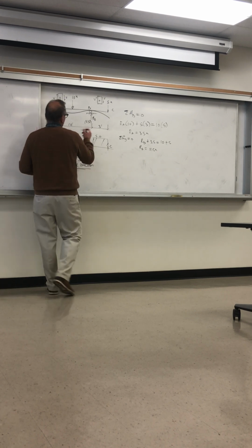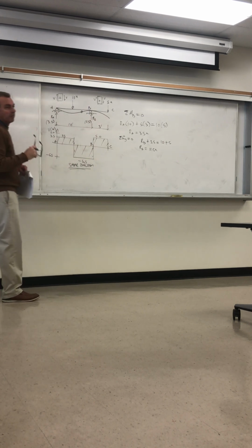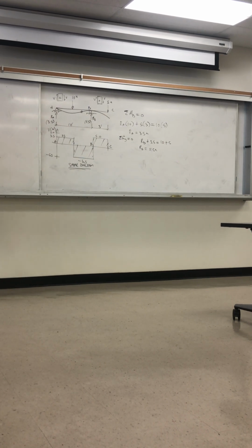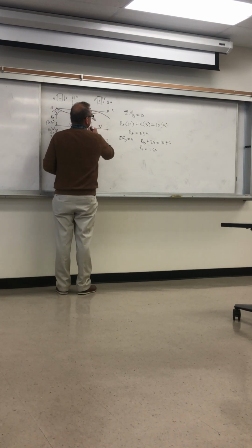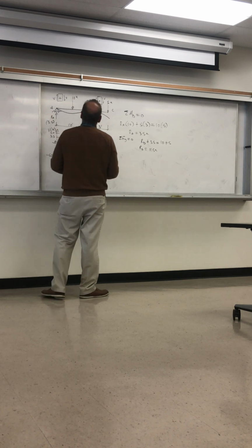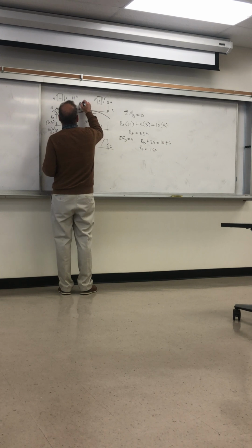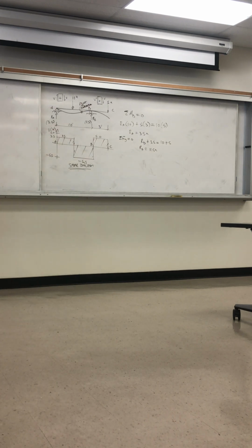I'm going from left to right or right to left. Let's solve for this. This is interesting right here. That's the point of inflection in the deflected shape. And that'll be the 0 moment location. So let's sketch the moment diagram.